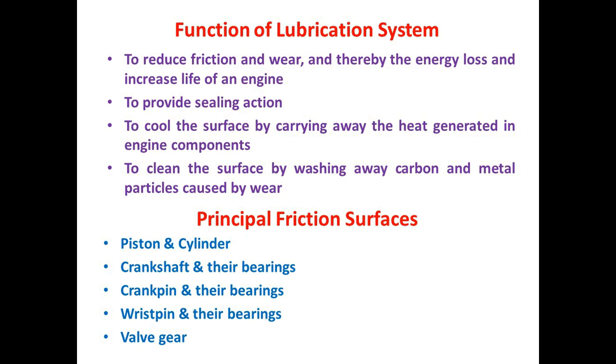The next point is, what are the principal friction surfaces or the major components where we have to focus as far as the lubrication system is concerned. The first component is definitely the piston and cylinder. Then we have the crankshaft and its bearing, crank pin and its bearing, wrist pin and its bearing, as well as valve gears. These are the major parts where we have to focus for the lubrication system.